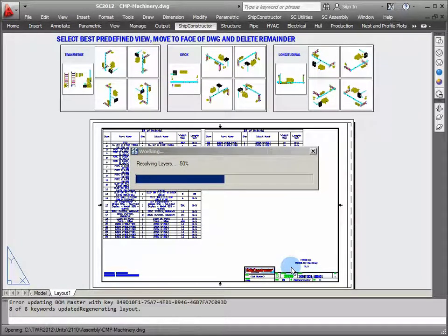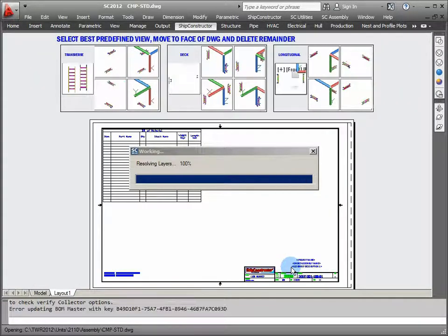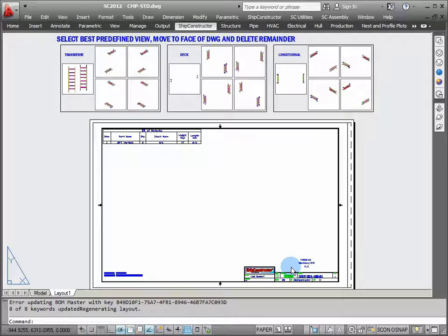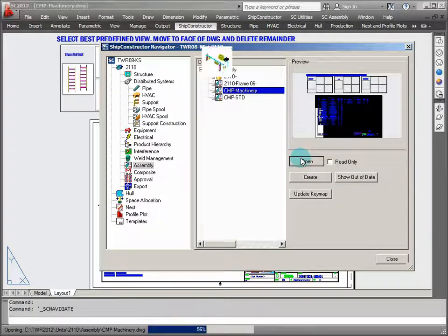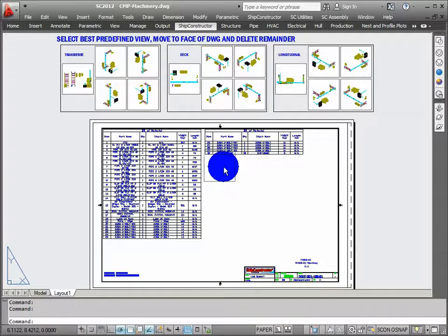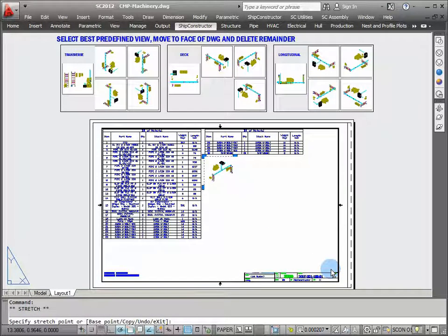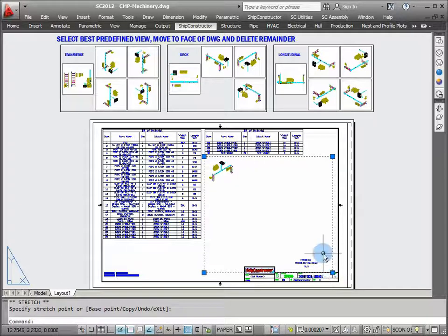That's easy. It's a piece of cake, because I can generate assembly drawings from alternate product hierarchies now. Meaning I can go in and say, generate an assembly drawing from the compartment product hierarchy, show me the machinery space. That's what that drawing was. Have a look. That's the machinery space we just defined. Only the parts in the machinery space we just defined. That bill of material lists every one of those parts, however I want to define it, broken down however I'd like to, with a view.